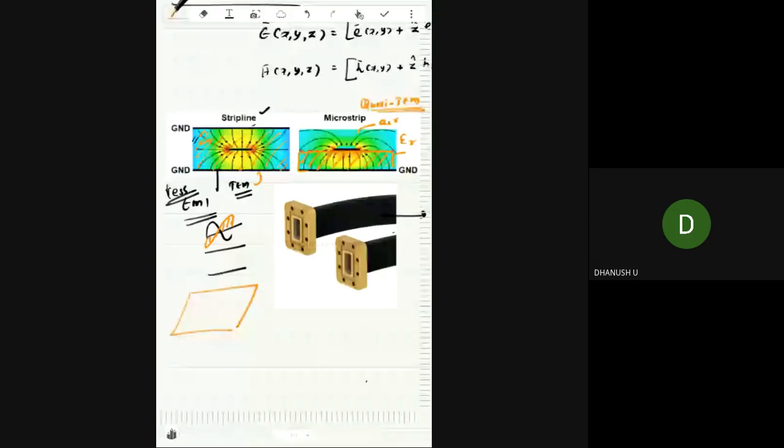That is what we do: the p-type, then the insulation, then the n-type, so that way we make the chips, right? Similarly, from the fabrication point of view, first I have to have a ground plane, and inside it I have to put the strip line. So I have to think about some lithography techniques. I put this dielectric medium here first, leave this space and do the metal deposition. Again I make the dielectric medium, and again I put the ground plane. It becomes one more step.